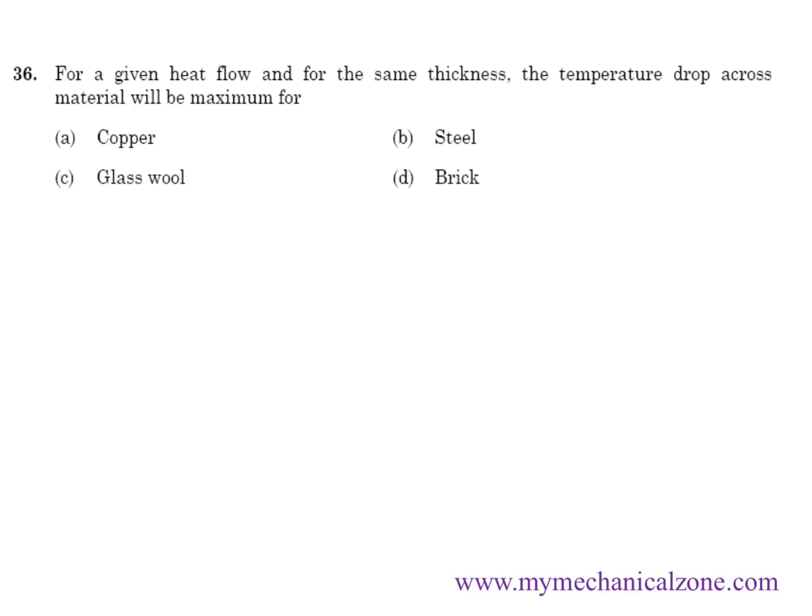So heat flow Q is constant, and Fourier's law of one dimensional heat conduction will apply: Q equals K times change in temperature over thickness. Since heat flow Q and thickness delta X are fixed, the temperature drop delta T is inversely proportional to K, the thermal conductivity.